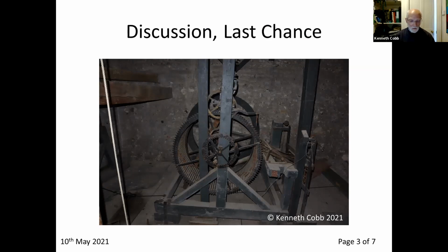The tune barrel, which is seen here, is about 1 meter in diameter. The tune barrel consists of strips of wrought iron set around the circumference, between which are jammed lifting pins. As the barrel rotates, the lifting pins lift hammer arms, which are connected to the bell hammers via hammer pull wires. The system works in a similar manner to a music box.